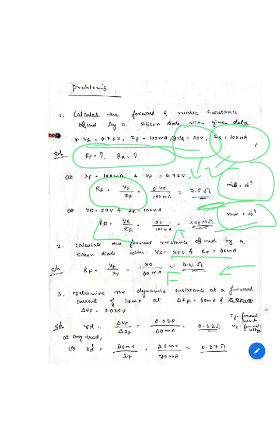Determine the dynamic resistance for a forward current of 70 milliamp at IF. Del IF, a small change in IF, is given as 60 milliamp and del VF is given as 0.025 volt. So RD is given by del VF by del IF. We know del VF and del IF. Just substitute and equate, you will get the value.